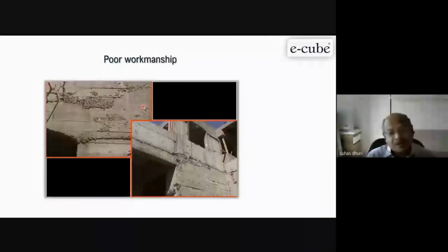If you compare, your concrete is working at, say, a water cement ratio of 0.4, and the plaster you are making is at a water cement ratio of 0.6 to 0.8. Then you can imagine the durability of that plaster. In real sense, plaster is not required for concrete. In all our infra projects and bridges, we don't apply any plaster. Only residential buildings get plaster. As I say, plaster is only to hide the defects. It's cosmetic.